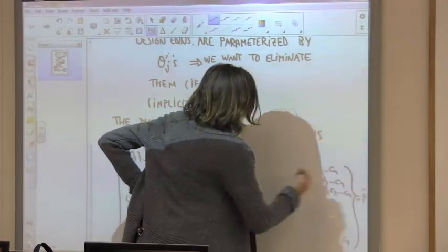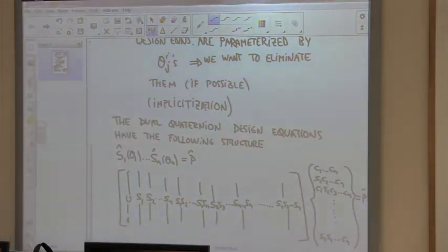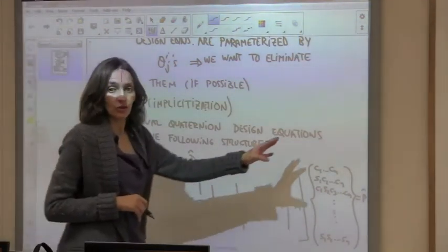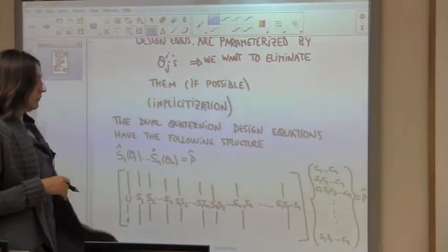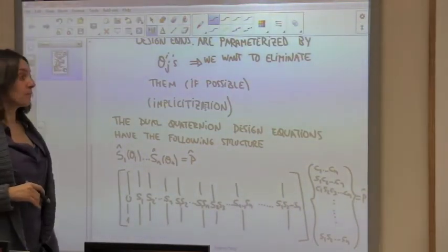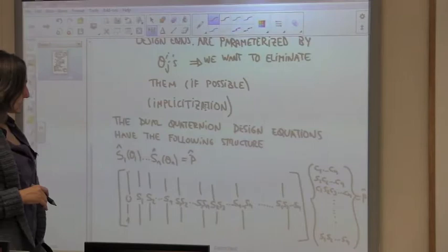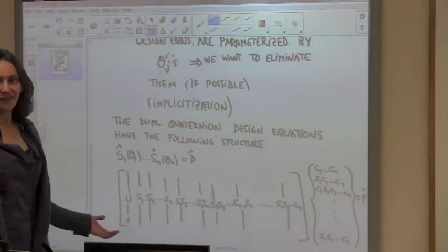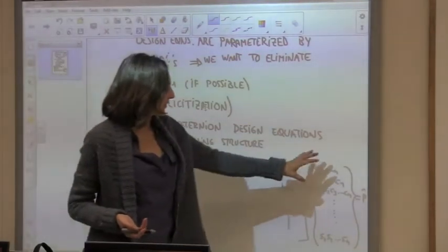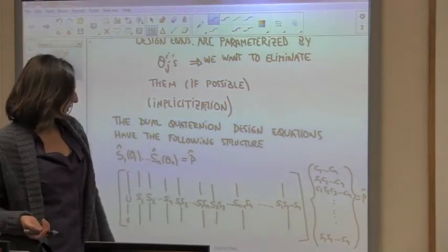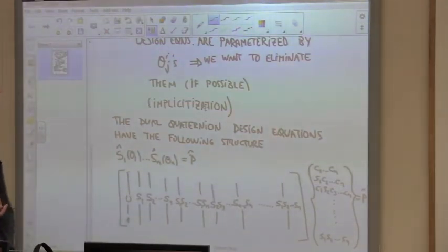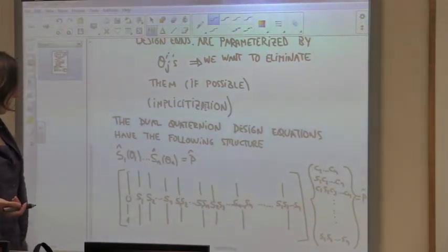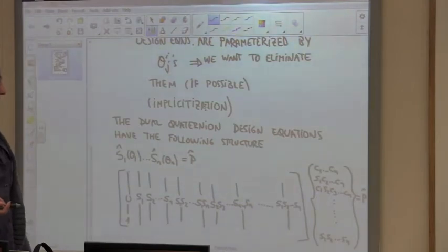So it has a nice way of separating the joint variables from the structural variables, which is very easy to do systematically. So we are done, right? We can just solve for this. We can do something like inverse kinematics, but this matrix you cannot always invert because it's not square. It's square only in a few cases for very low degrees of freedom, so it's not so easy.